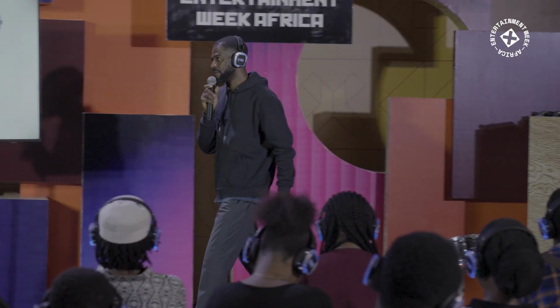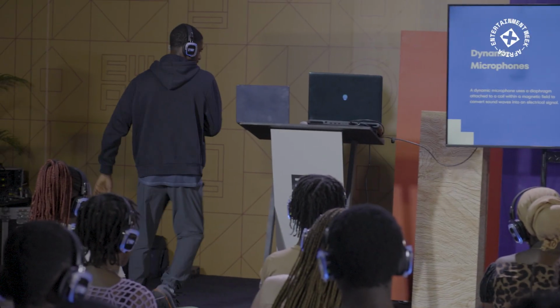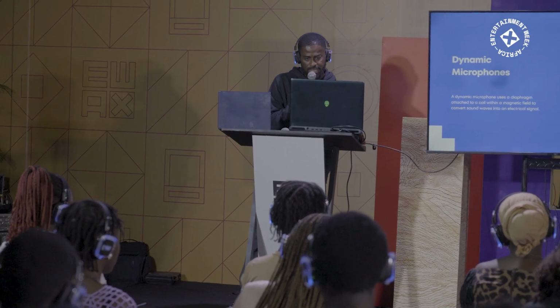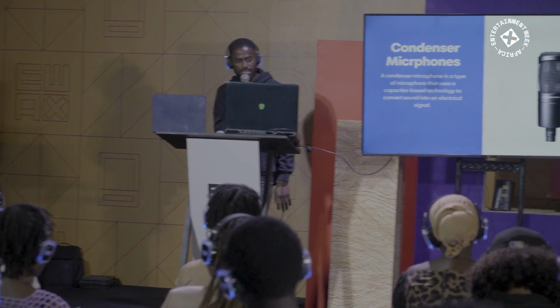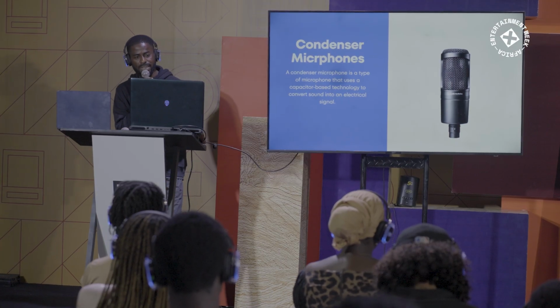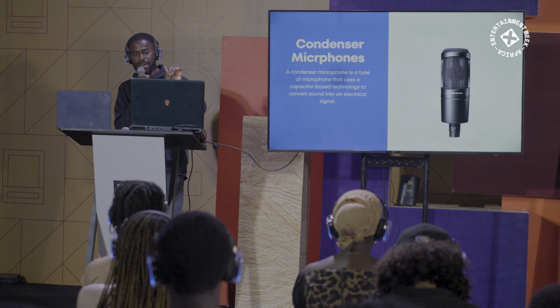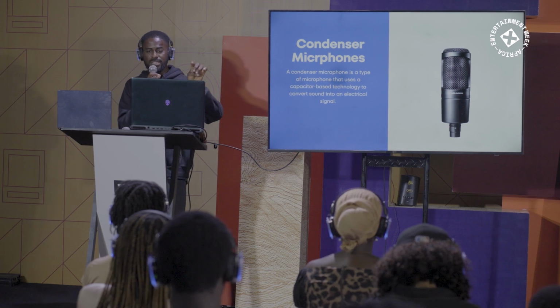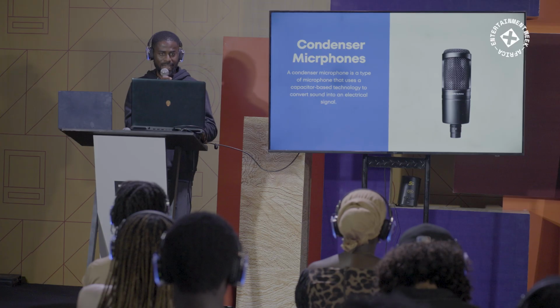The next microphone would be a condenser mic, I think, on my slide. Let's see. Yes. So a condenser microphone is a type of microphone that uses capacitor-based technology to convert sound into electrical energy. Now, with a condenser microphone, we need to apply 48-volt phantom DC power for it